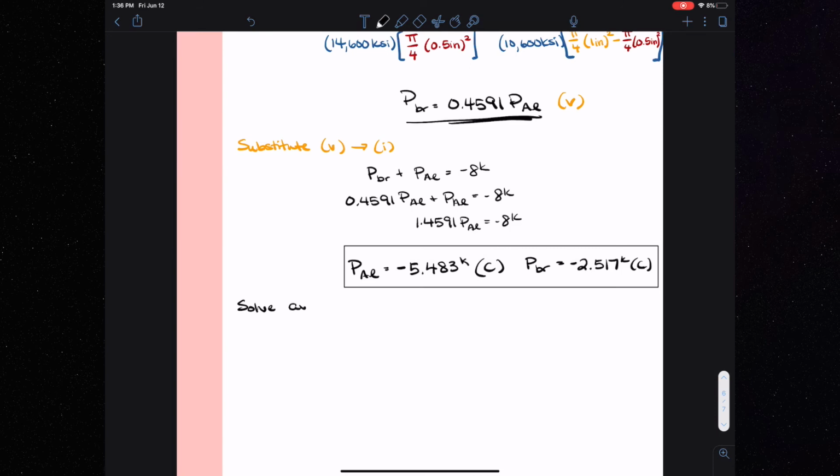So we have to learn through practice and being able to identify the statically indeterminate nature of these problems, so that we know when we have to use our engineering toolbox and solve a statically indeterminate problem versus other cases where it'll be statically determinate. Our final step in the problem is then to solve the average normal stress. The average normal stress, as you recall, is sigma equals P over A. So I need to do this for both the aluminum shell and the brass core.